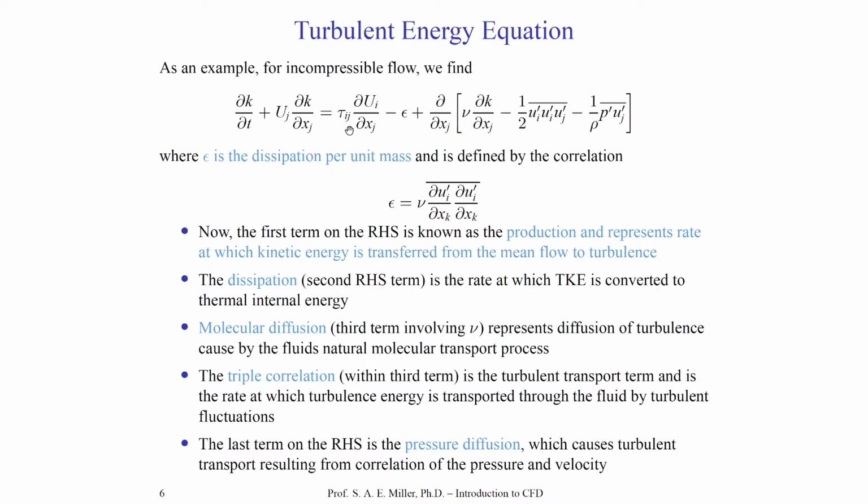Of course, there's viscosity in tau ij, and there must be a viscous term too. So this term here on the right-hand side is where turbulence is being produced. That's why it's called the production term. Mind you, the second term on the left-hand side is just like a convection term. It essentially moves the energy through the flow.